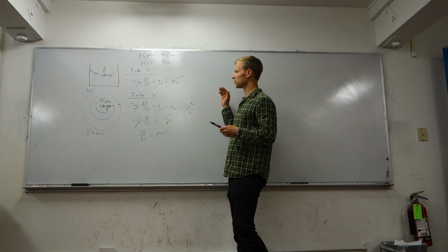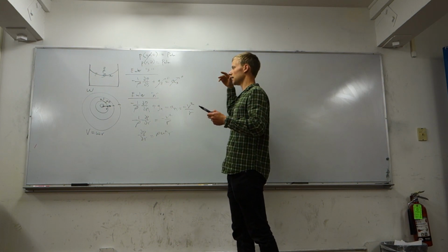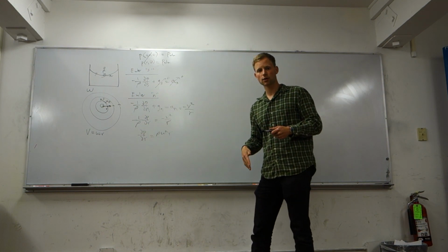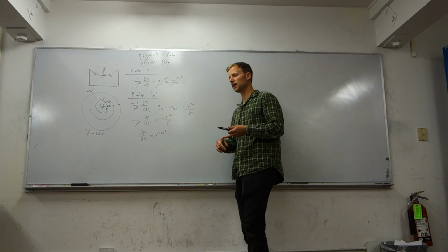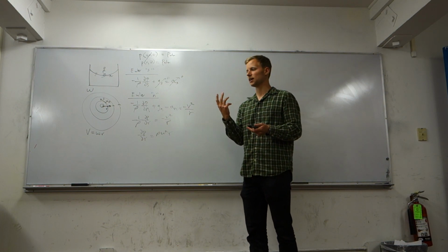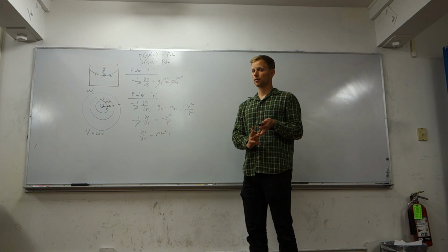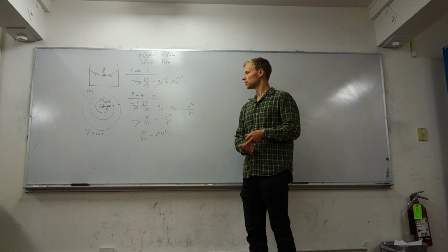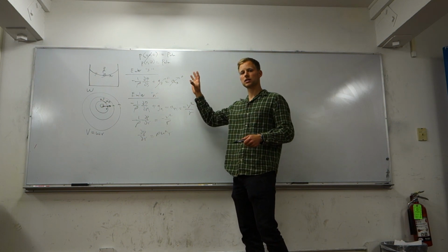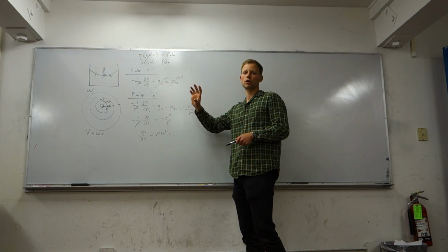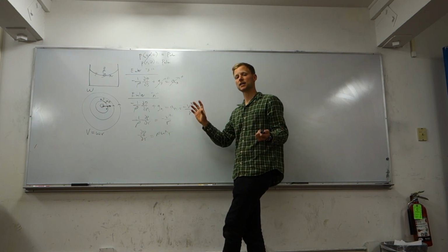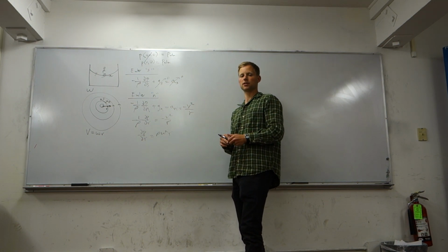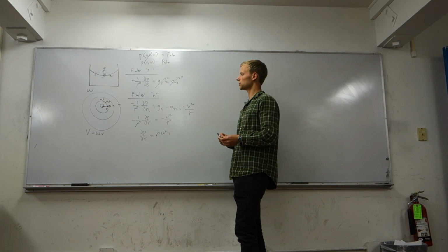In order to simplify our lives, we take the Navier-Stokes equations and call it inviscid, and we have the Euler equation. And then we can simplify our lives even further to get Bernoulli's equation by dealing with steady and inviscid again, along a streamline, and we're neglecting any frictional effects. We said inviscid. So the general hierarchy of equations goes Navier-Stokes is the most general, then Euler equations, which we've written here in the s and n direction, but they could be written in x, y, and z just as well, or r, theta, and z in that case. And then Bernoulli's equation is the bottom of the chain of those equations.